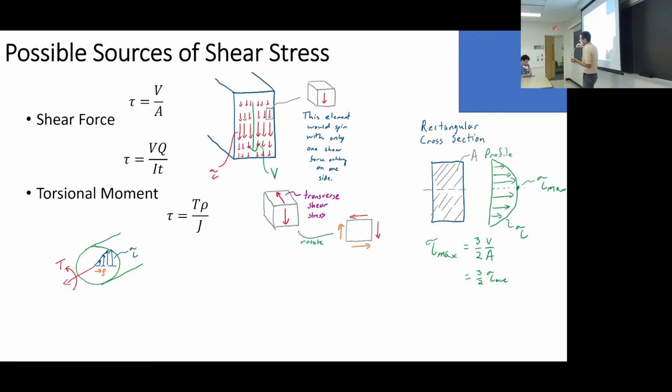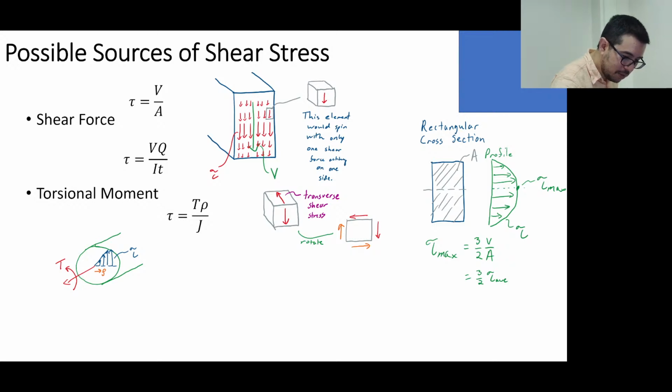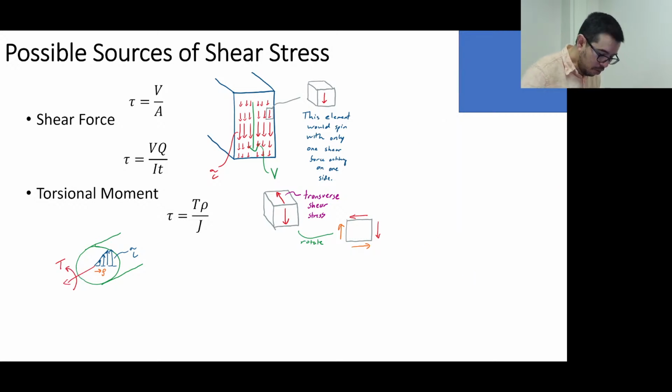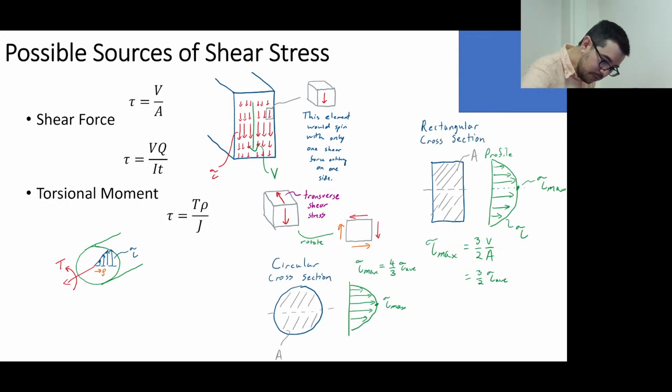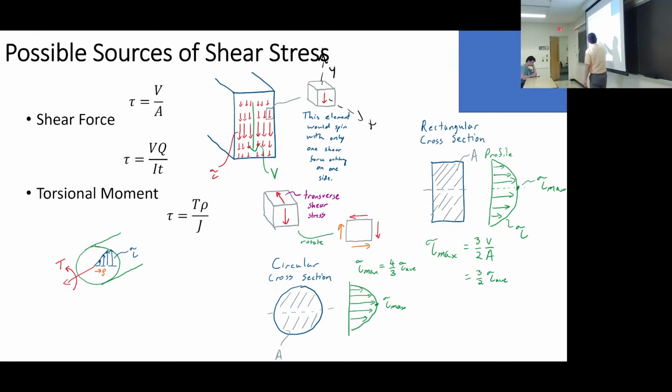These arrows attributed to the shear stress are acting the way I said a minute ago. Let me just draw a messy picture. If I have x and y, do you see that this shear stress is acting on the x face? On the top line, these combined 4 arrows are acting on an x face and a y face. But they're acting parallel to those faces, so they're shear stresses.